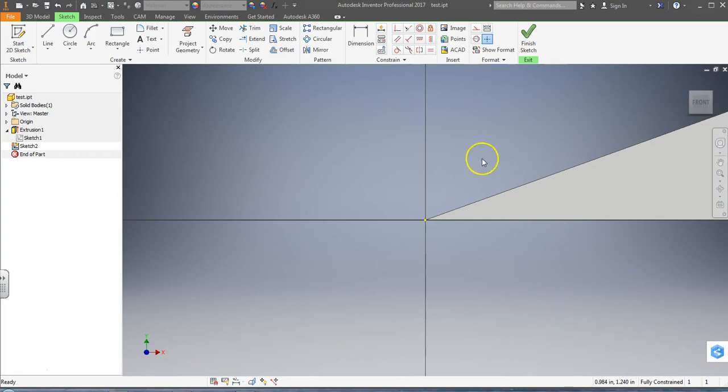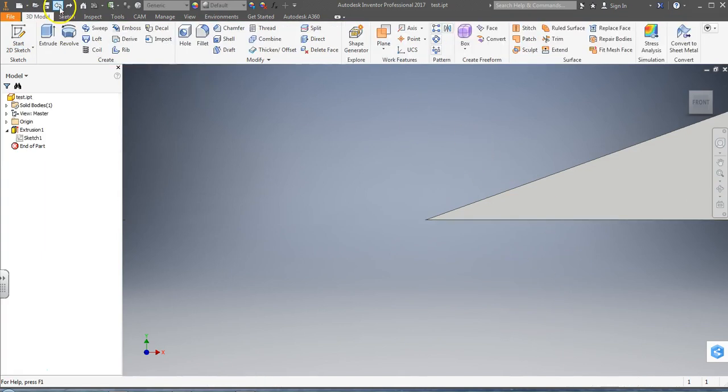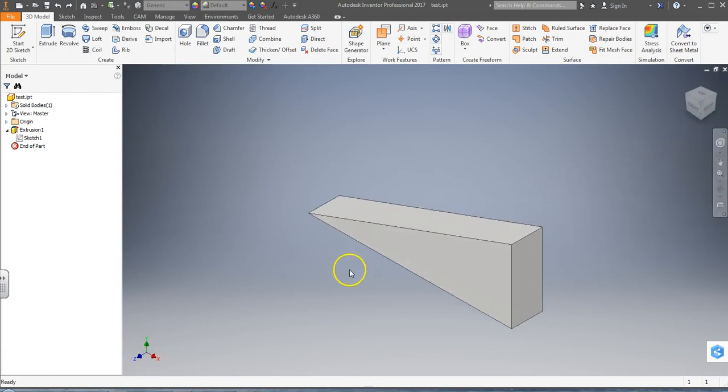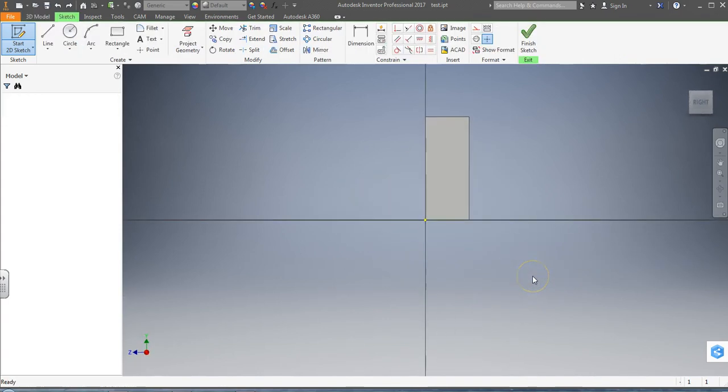I take that back. Let's say I'm not going to put it on that surface because that's kind of obvious, okay? That's logical. Let's say I'm going to put it on the end here. That's a surface I wasn't working on before. I can do that. Sketch, 2D, pick this surface. It rotates the part around and makes it flat to the screen.